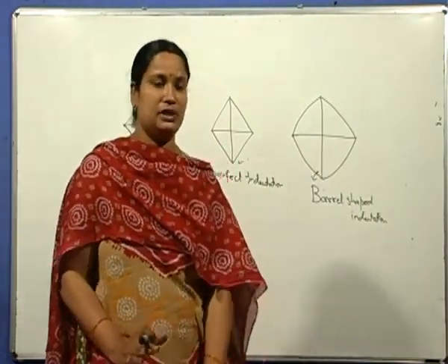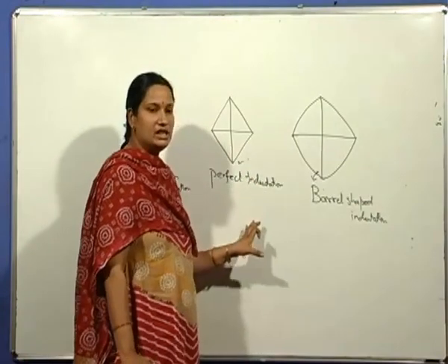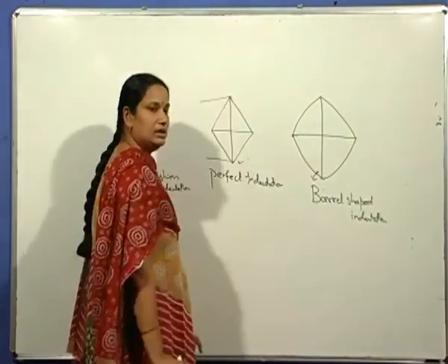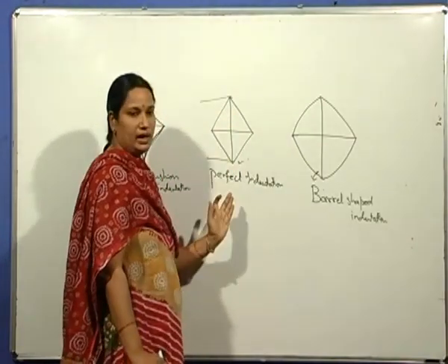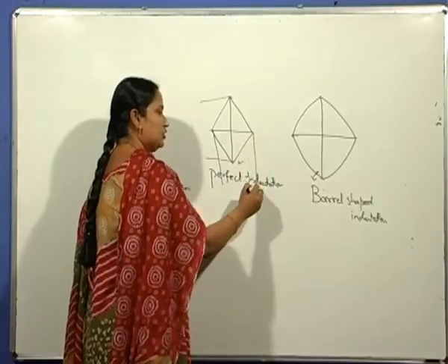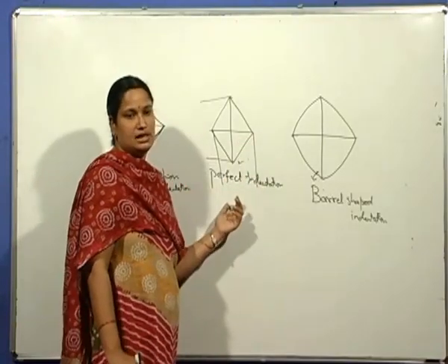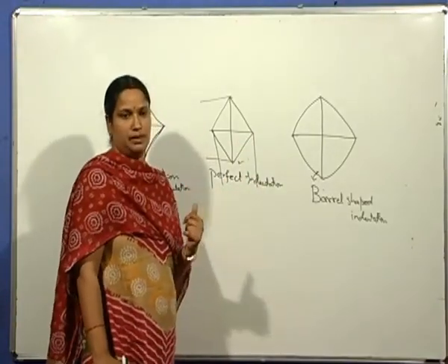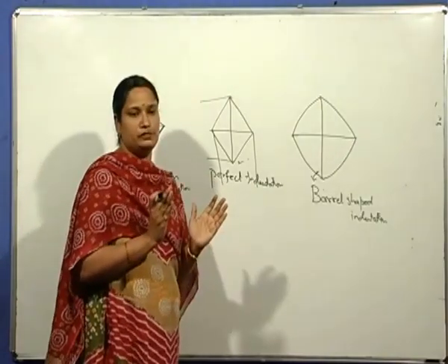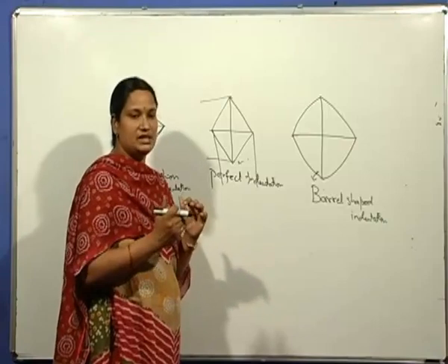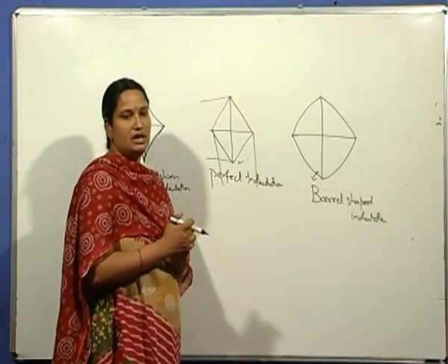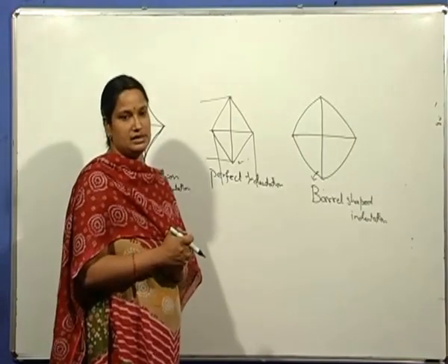So when one obtains a perfect indentation, one measures the two diagonals, diagonal 1 and diagonal 2, and the average of these two diagonals is taken and substituted in the formula. One should be very careful in measuring the lengths of the diagonals, because any error in measuring them will result in incorrect hardness readings.